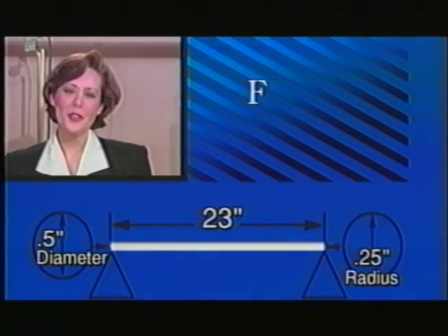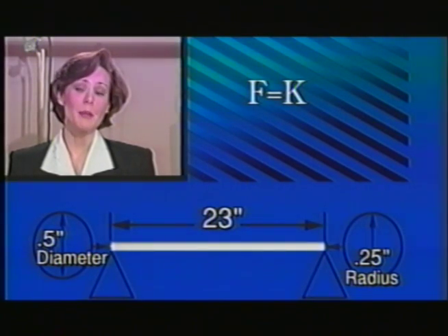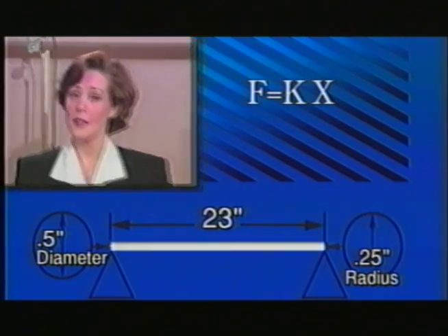The force would be 4 pounds if the weight were not moving. We are going to drop it from just 1 inch. Now we don't seem to know the force. Wait, let's use Hooke's law. Force is equal to the stiffness of the beam multiplied by the deflection.